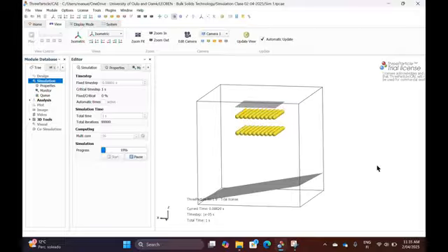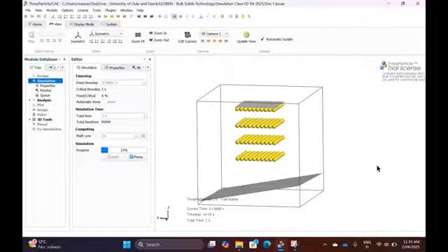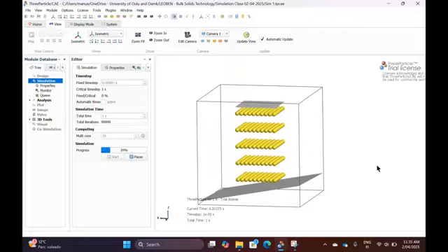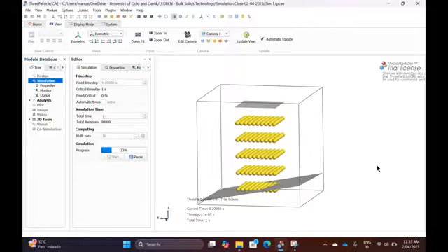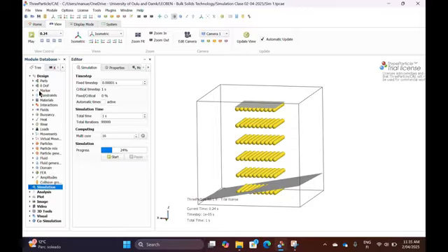Right. We said we need a Hertz-Mendel contact model, something similar, so that the particles know that they actually contact each other. So we go to interactions. Oh, yes, there is something missing. Rock has no interaction, and rock steel has also no interaction. Nothing defined here.